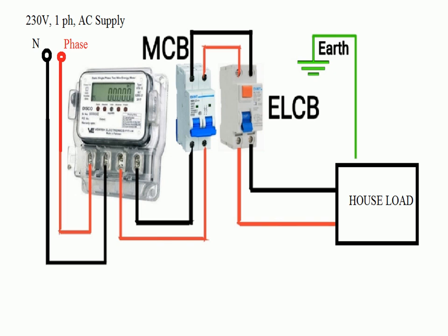So it is the main MCB, because if any fault occurs, this circuit breaker trips. Each room may consist of different circuit breakers, MCBs. Those are referred to as sub MCBs. Sir, earth connection is also required. We have to give the equipment earth protection from the meter board.